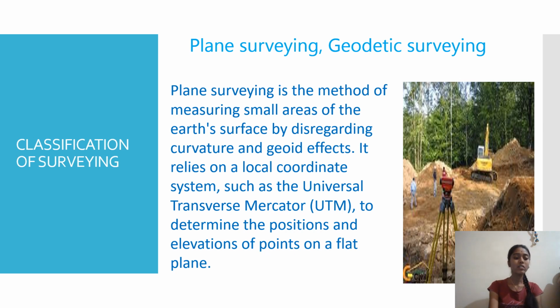The surface of the Earth is taken to be a plane surface in plane surveying. The extent of area up to which this assumption of plane surface holds good is about 260 square kilometers. Therefore, plane surveying is adopted for small areas.